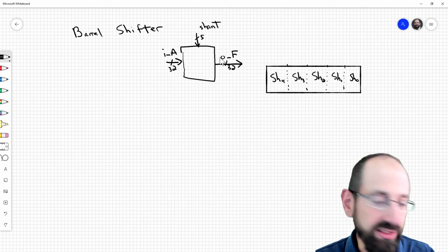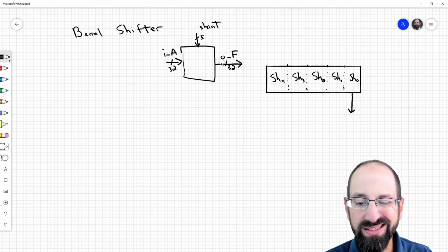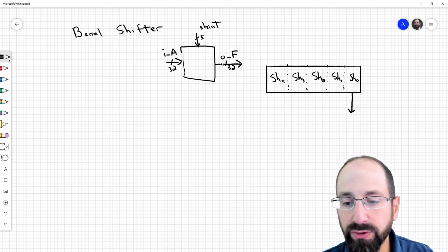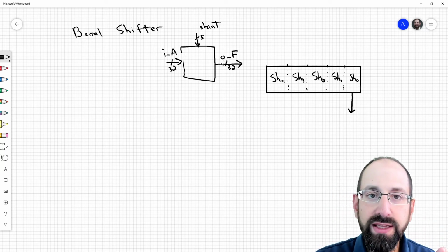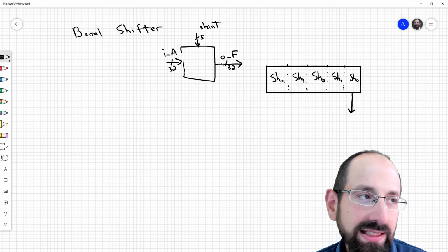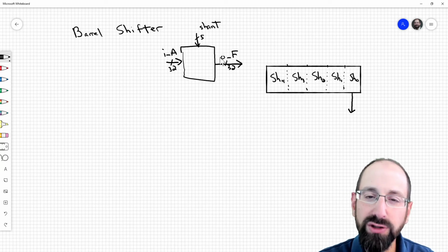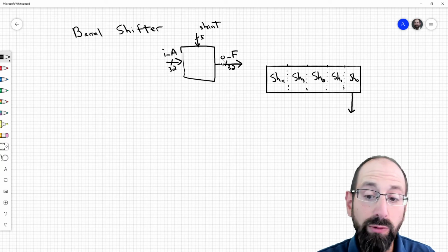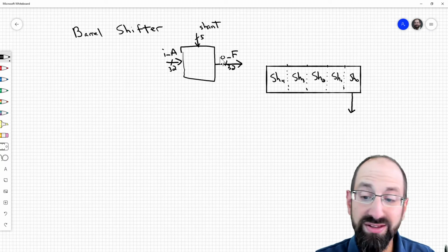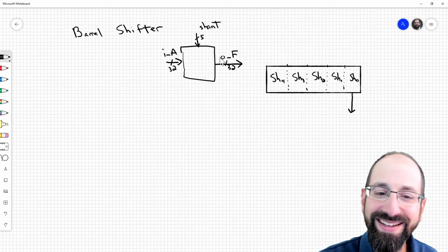Let's imagine, as we look at just the first bit, shift amount of 0, what would our design look like? What would be one way to implement just a single bit shifter? This would be just for a single bit of control, a binary shifter. It takes a 32-bit input and shifts it either 1 bit to the left or not at all. Well, how would you implement that? You can think of it in terms of behavioral logic that would make sense to you, but if we think of it in terms of components and functional units and how we would lay them out, you can think of that 1 bit shift as being basically a mux. Should my output be the same as the input, so shifting 0, or should it be the value shifted over by 1?